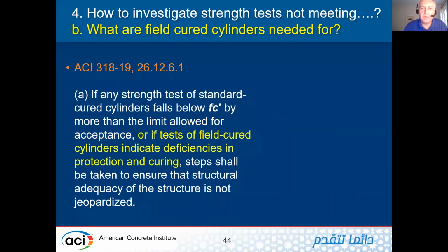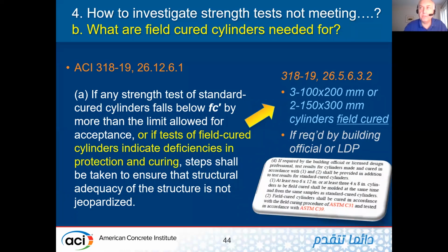Or if the test of field cured cylinders indicates deficiencies in protection and curing. Now you say, hey, there's nothing about field cured cylinders, they are not part of the strength test, and that's true. But building officials may require field cured cylinders, or the licensed design professional, and LDP is meant as the engineer of record for some of you who use that term. They may specify field cured cylinders for other reasons than the strength test. So in other words, if you have them available, you can look at them.